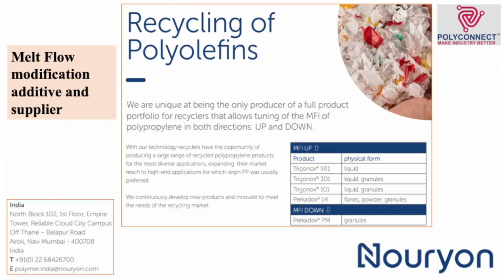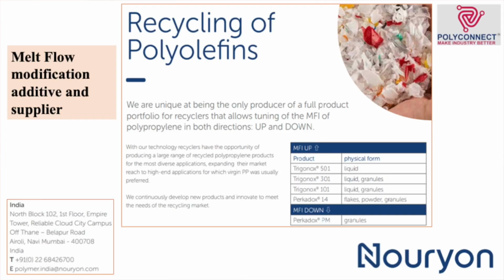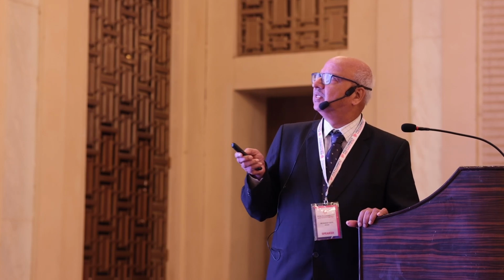Recycling polyolefins, where we have mainly mixed waste, we cannot modify it to our requirement. But now certain additives are available which can change your melt flow index, which is a major issue while processing recycled material. Waste is not available in a pure form. It is always available as mixed waste. There, these melt flow additives can change your melt flow index and processing becomes easier.